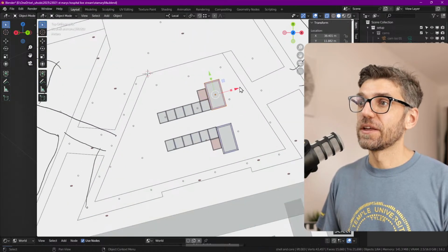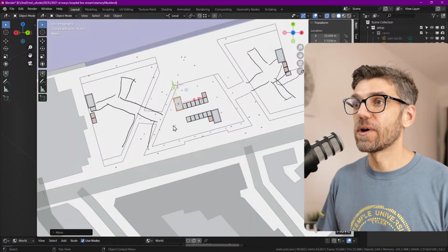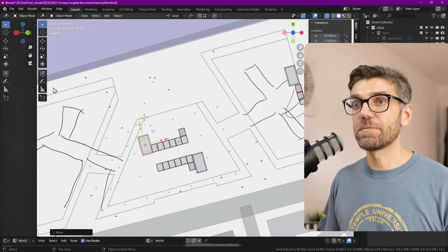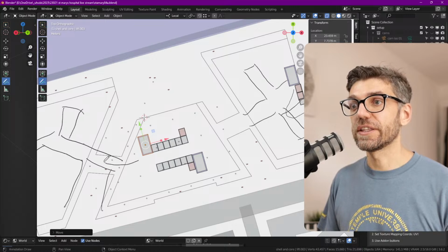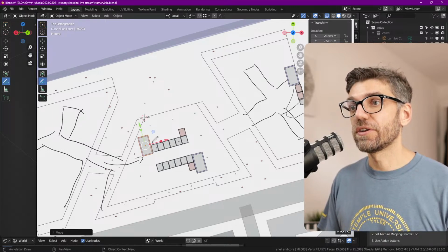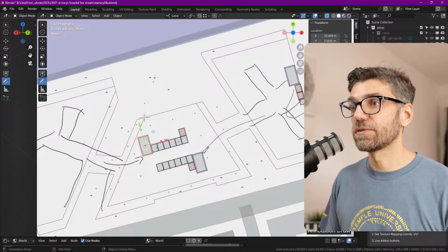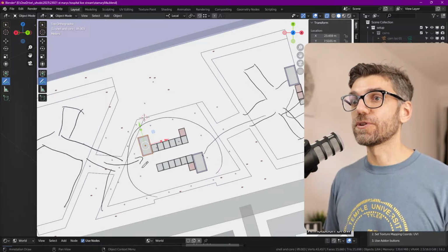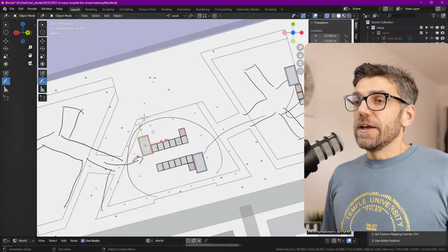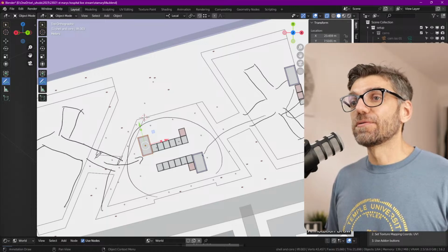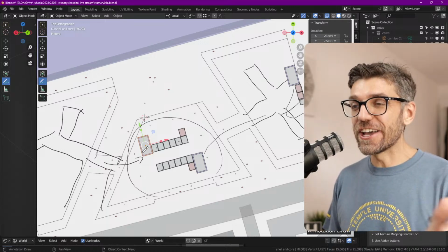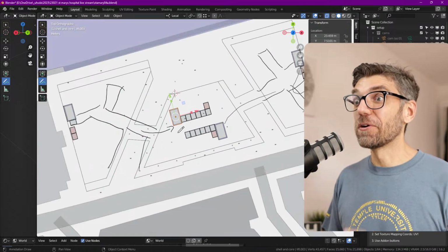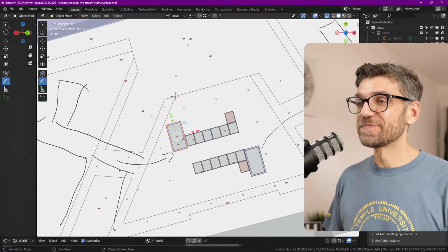So one thing that can definitely help is having one of these fire cores over here, the stair core. In this case, the people that come from this side are kind of close, right? So they can use that, and then the people that come from that side can also use that. So it's not only for the people in this building, but also for those people in that building. Okay, well, yeah. Other challenges, I won't get into it because you can spend all of our time talking about that. Want to get the basics.